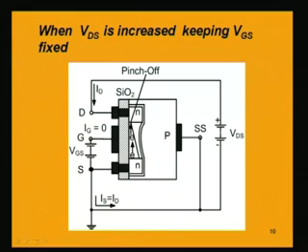So, the width of the channel basically depends upon the attractive force on the electrons by the gate to drain voltage. If this gate to drain voltage reduces, that means the attractive force on the electrons also reduces. That is why the width of the channel will be reducing from source to drain.